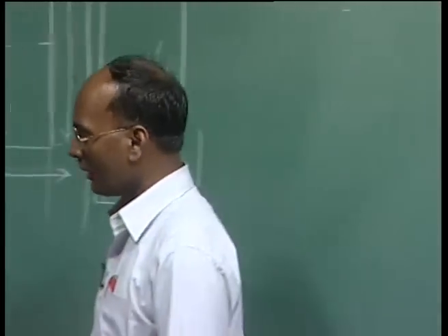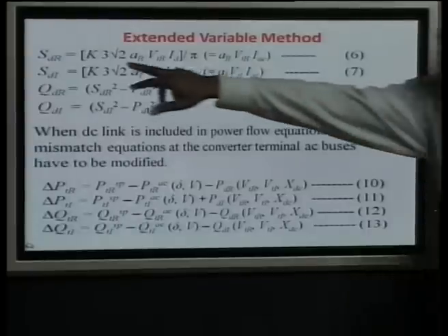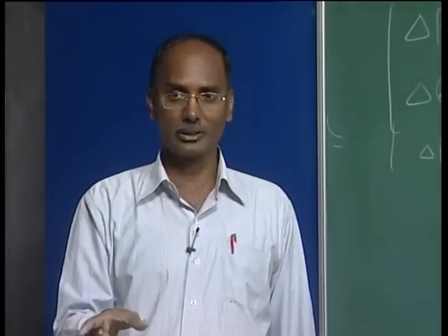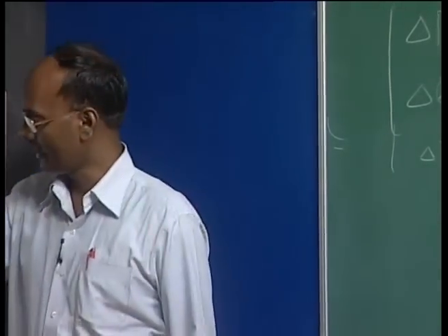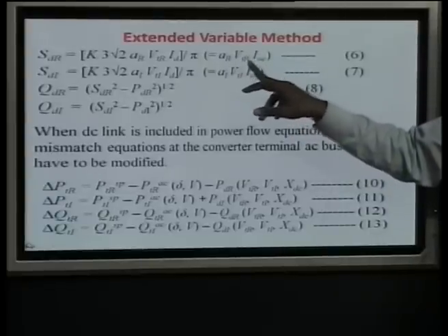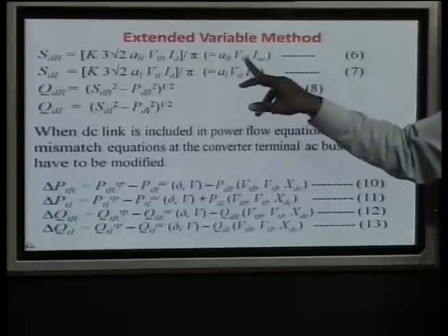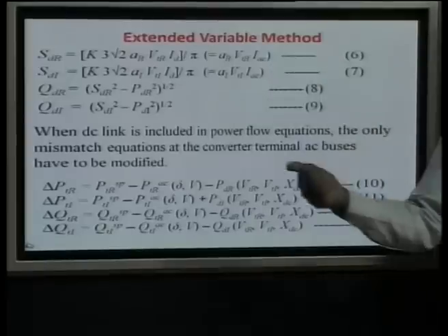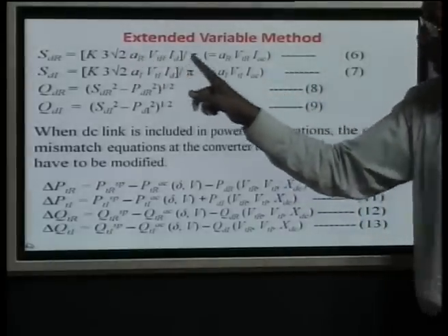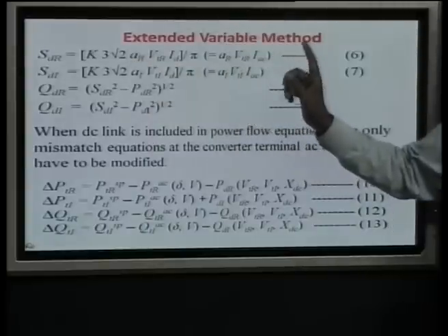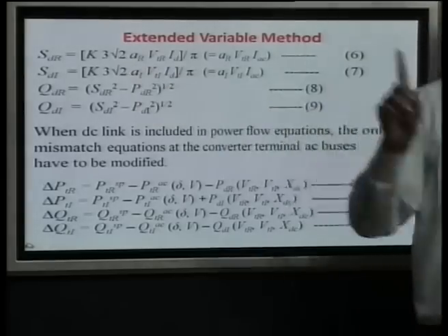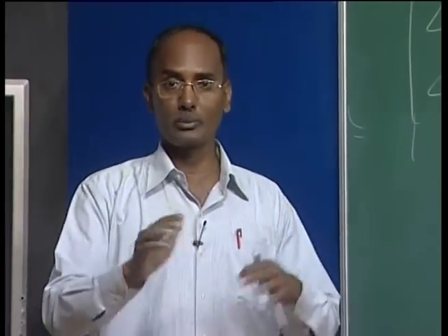So, here I wrote the complex power at the rectifier terminal taken by the DC system, that is a converter. Here we can write AR, this is the rectifier OLTC, this is the terminal voltage where we are calculating this, and IAC, that is the current going there. So, if you put the IAC value here in terms of DC, you are going to get, as we already proved here, since we are writing in the per unit, mind it, this k term is appearing, again you are taking it as 1 or this, because now every base should be the same.